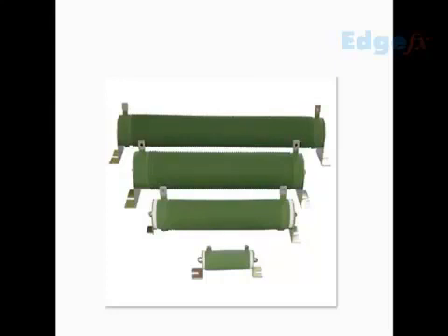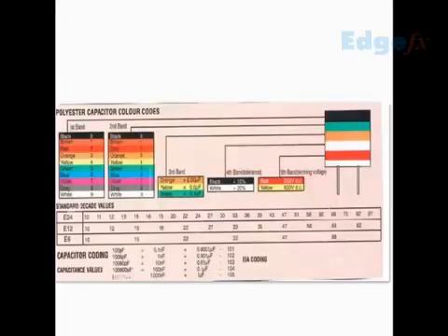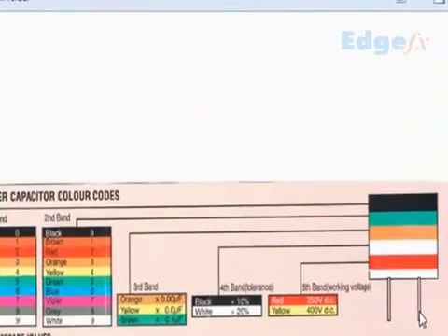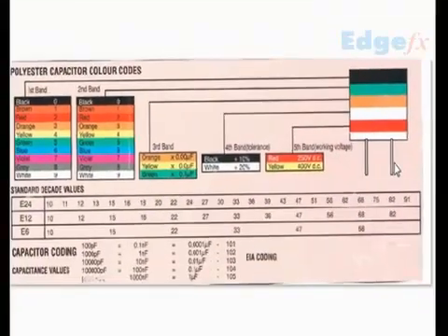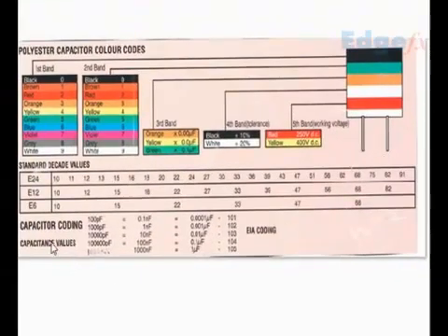And as for identifying the group of capacitors which is not electrolytic, for example, this is also a typical capacitor, where these are not polarized, these are non-polarized capacitors, and the non-polarized capacitors are mostly in the area of ceramic capacitors, polyester capacitors, and so on. Here the color coding is somewhat similar to resistor type, but the numbering types are also very popularly followed.